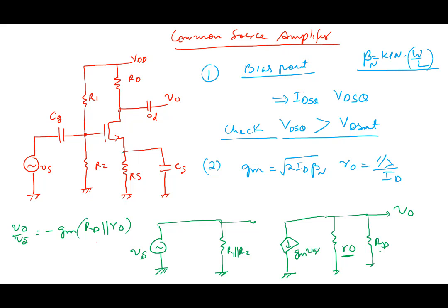So, yeah. If the body and the source are not shorted, how do you calculate GMB? There's a relationship I've not given you. GMB would be equal to something, say sometimes eta times GM. There's a relationship. Most of the time we will not deal with it, so that's why it's not given. So GMB is related to GM, okay? So a straightforward substitution: replace the transistor by its model.